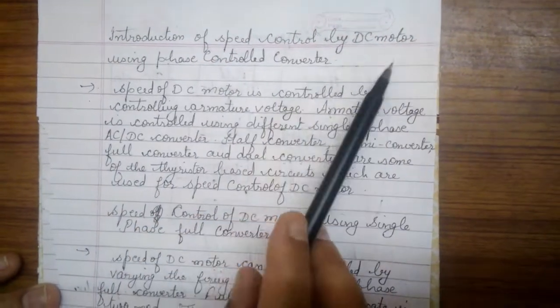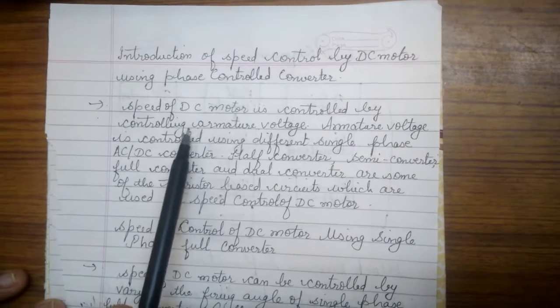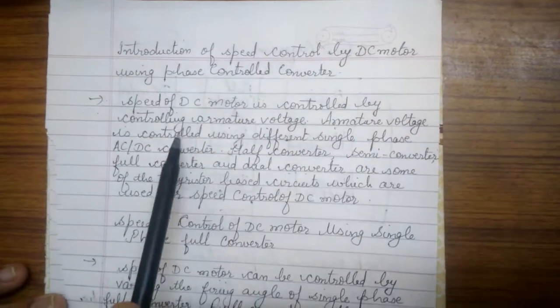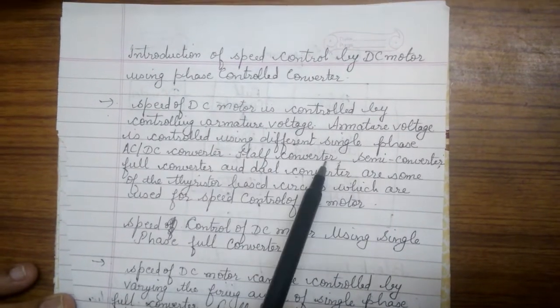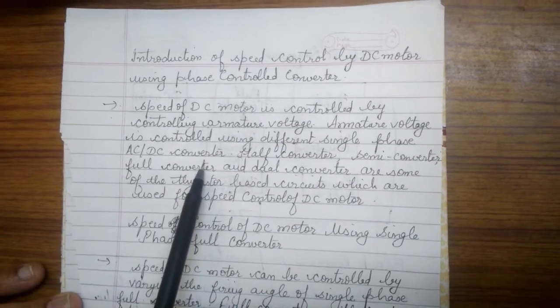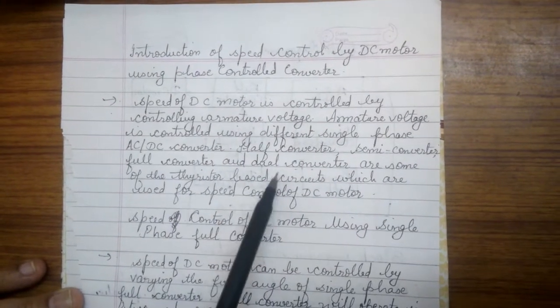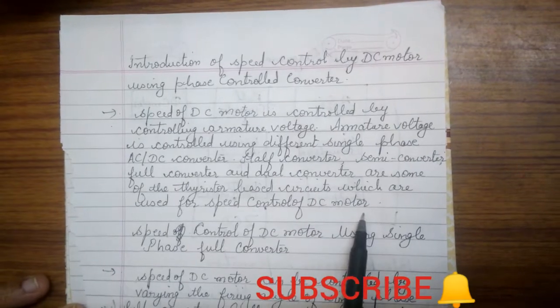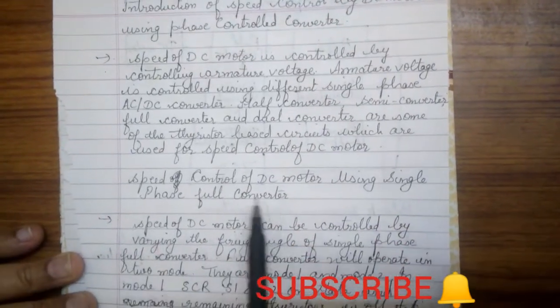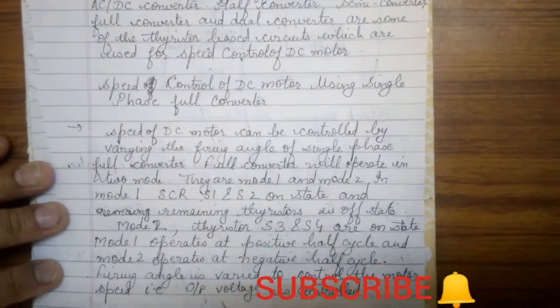Speed control of a DC motor using the phase control converter. The speed of a DC motor is controlled by the armature voltage, and the armature voltage is controlled using different single phase AC to DC converters. Half converter, semi converter and dual converter are some of the thyristor based circuits which are used for the speed control of a DC motor. Now the speed control of a DC motor using the single phase full converter.